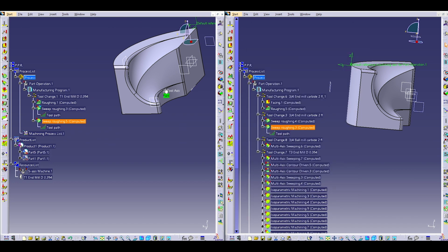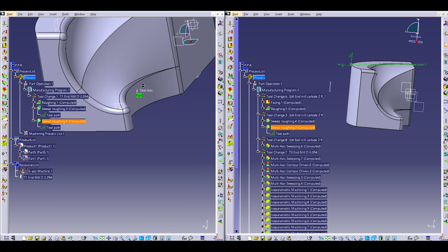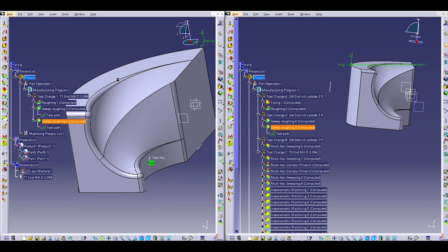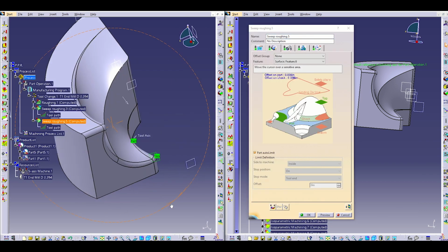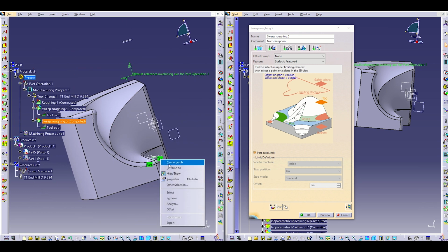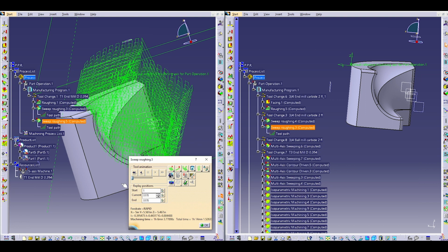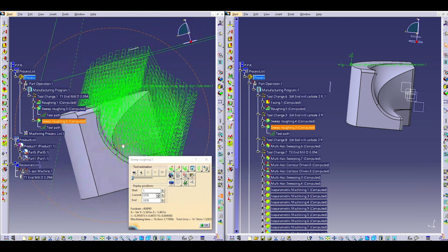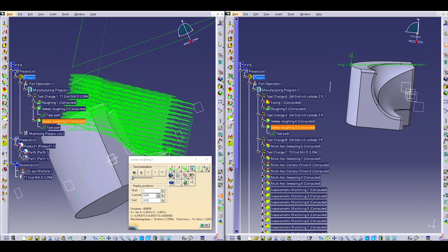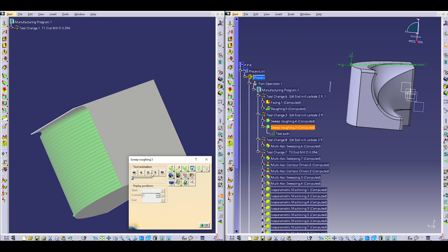So what I'm going to do is change the top of the part. I'm going to offset a plane, and I'm searching for something I can use. Oh, and there's some in the corners. There's like a point. You can click on that. It'll create a plane, and then I'm going to offset from that plane a couple inches outward. You can see it's starting to get bigger there, so that way we're not running in. You can use that to not run into the part. That's a little better, you can see. I think we'll probably go with that.